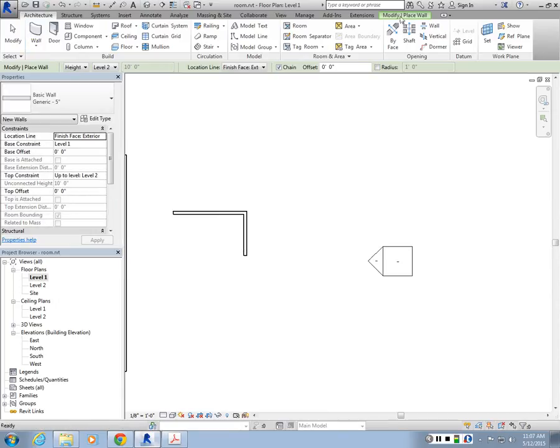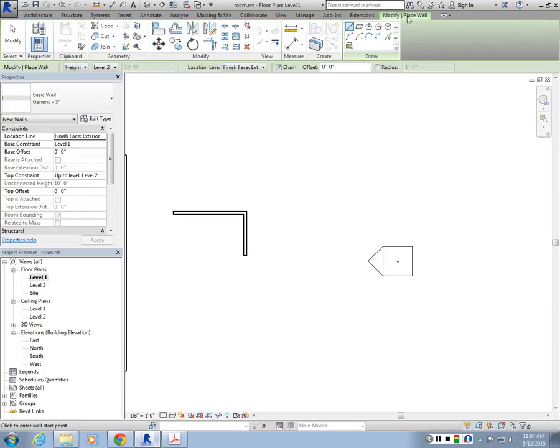If you select wall again, go to modify place wall, context ribbon. The highlighted green is an object specific tool. There are other types of geometry options here that you could use as well, like the center ends arc tool, for instance. And the preview shows you just how that would work.